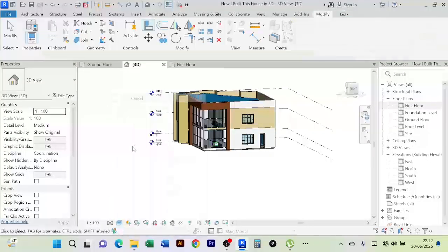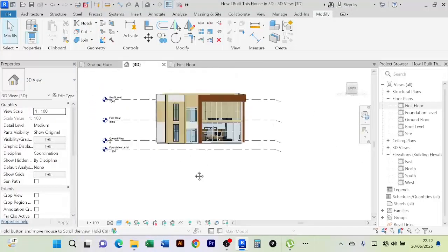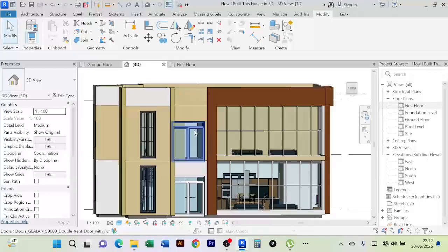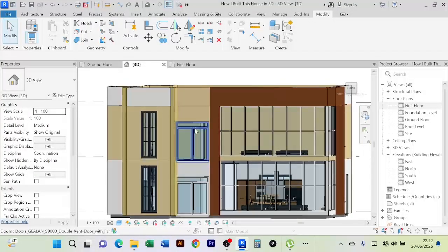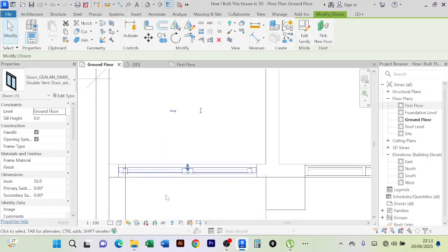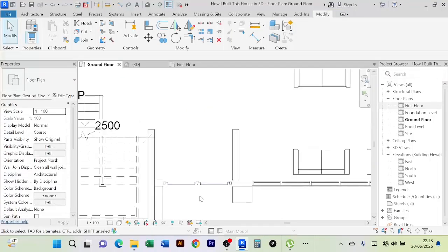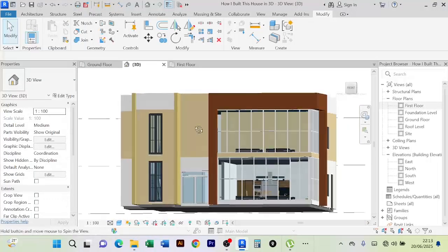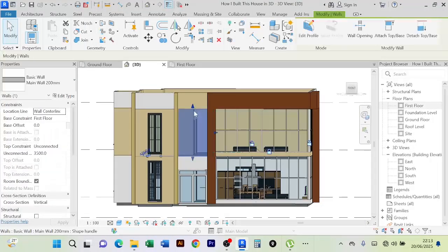So now remember I said I wanted to create a curtain wall here, because this door does not make sense here, since it's not supposed to be a door. So I'm going to delete it just like that, but I'll come to my ground floor. I'll make sure this door is not covered by this extrusion. So I'll bring it a little bit here, just like that, so that the extrusion doesn't really swallow it up. Then here you'll see it is there unaffected.